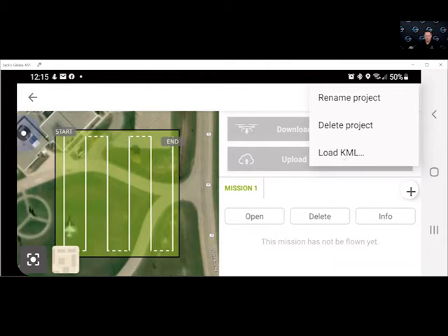So again, if we're sitting at the office getting ready to go out for the day and really want to define our lines, we can actually go onto Google Earth Pro and make an outline, basically a KML file, of the shape of whatever we want to capture. So if you know that you've got defined areas that you want to capture, you don't want to go too much over that, because obviously any extra flying we do takes extra battery, takes extra time, takes even longer to process. So we can actually put an image down from this KML on a map that will allow us to see where we want to keep the aircraft when we're doing flight planning. So it's a nice little tool to use.